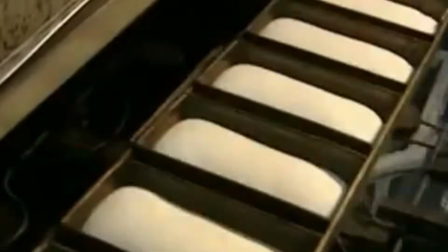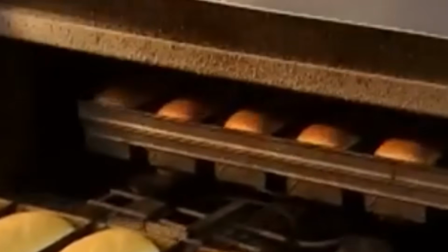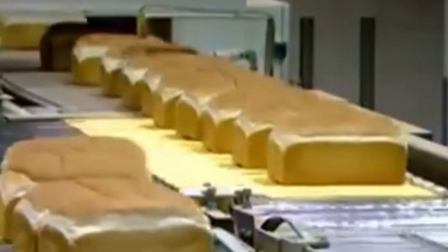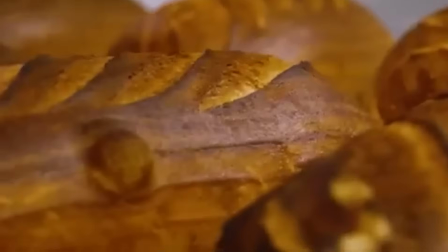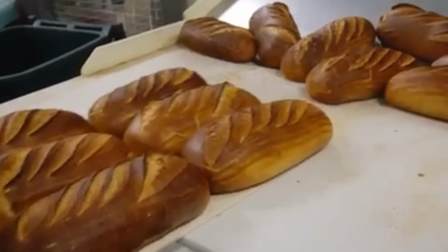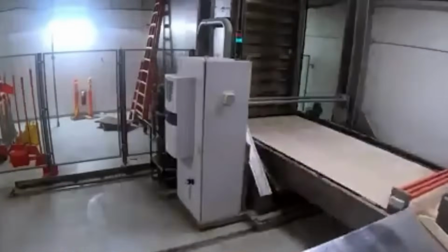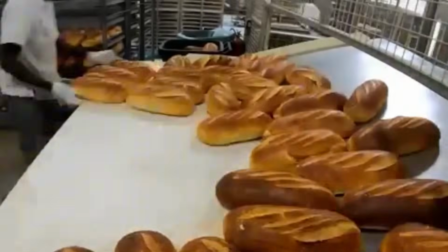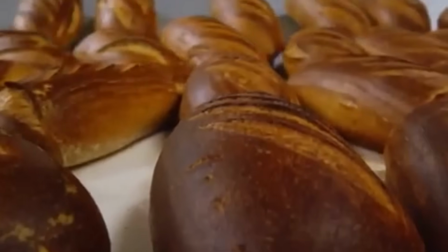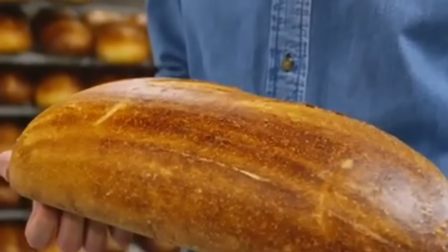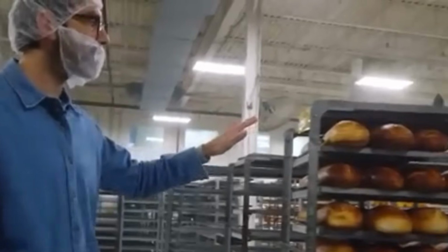Each pan is pre-lubricated with a fine mist of oil dispensed by a jet spray system to ensure clean release after baking. At this point, the pans pass through the final proofer, a long, enclosed tunnel where heat and humidity are kept within strict boundaries. Here, the loaves experience their final rise, swelling as fermentation accelerates. The gases trapped in the dough expand, the gluten matrix stretches to accommodate the volume, and the surface tension pulls tight, smoothing the top into a rounded dome.